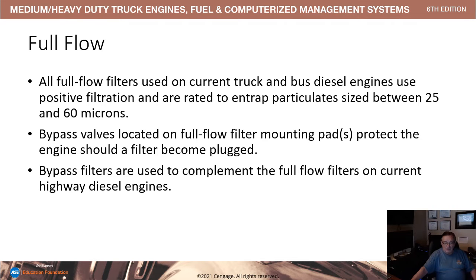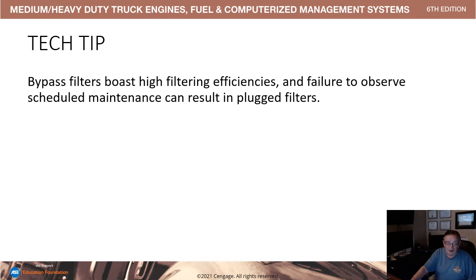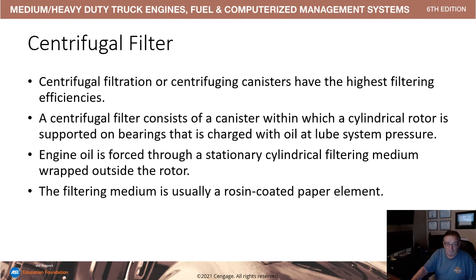Bypass filters located on full flow filter mounting pads protect the engine should a filter become plugged. Bypass filters are used to complement full flow filters on current highway diesels. Tech tip: a bypass filter boasts high filtering efficiencies, and failure to observe scheduled maintenance can result in plugged filters.